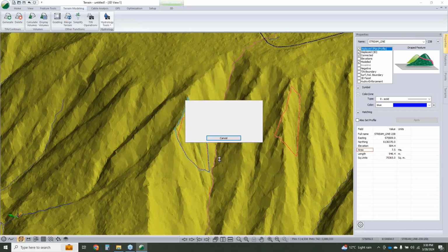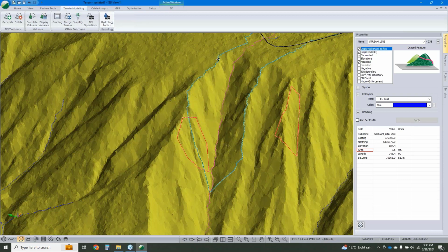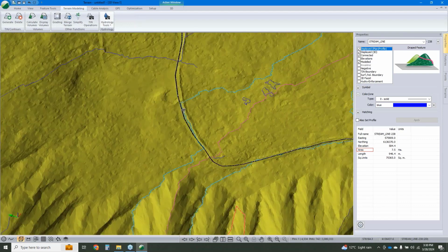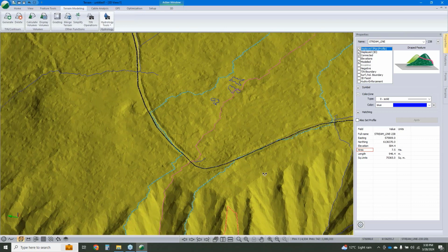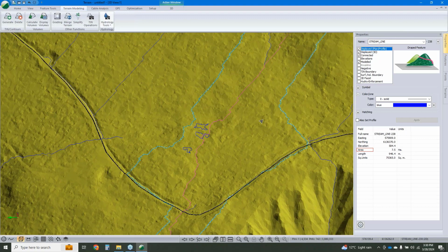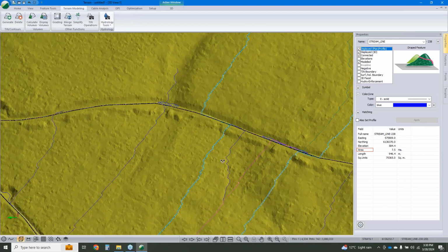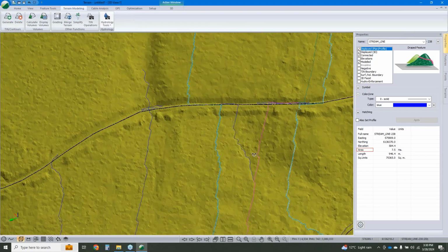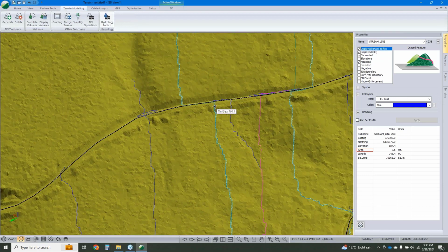We're going to see how the roads upslope of this interact and capture and redirect our flow. So here that looks all good and normal. And then for this first road, well, we can see we're catching a bunch more flow than we probably would have without the road there in the ditch. Same with the other side. So rather than just being a little polygon like that, we're getting a whole lot more area off to the side. And then we go up even higher and same thing. So being able to account for that kind of merged surface is going to be useful.